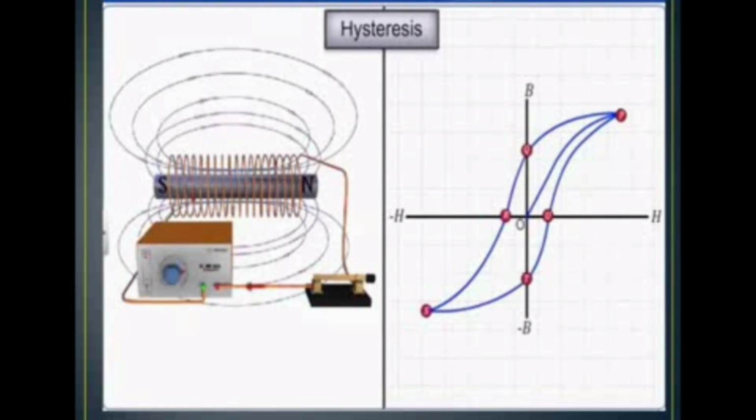So the hysteresis loss, you can write it as delta E equal to the closed integral of H dot dB. That is explained by the hysteresis loss. So using that we can find out hard and soft magnetic materials. Suppose the graph has a very large area, that is called a hard magnetic material. If it has a very small area, that is a soft magnetic material. So using that hysteresis loop, we can find out the hard and the soft materials.